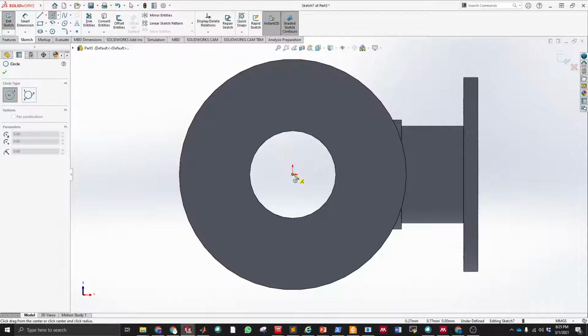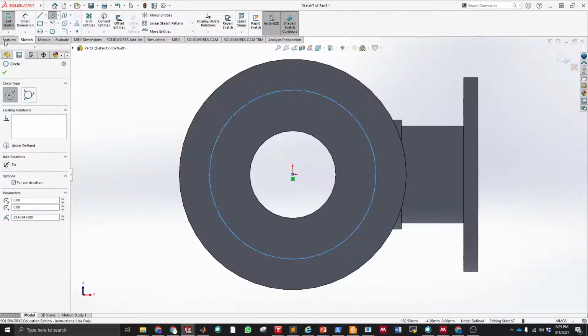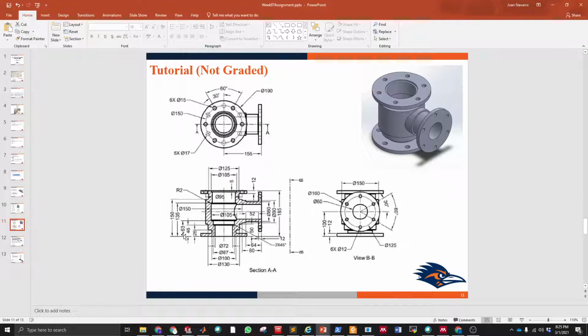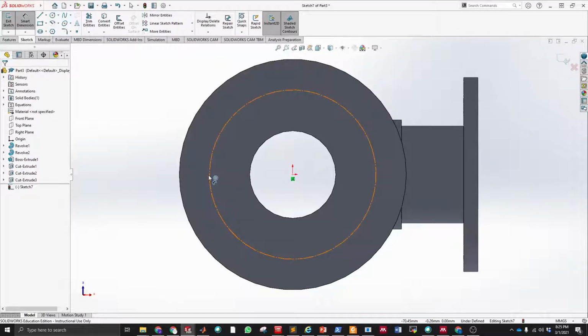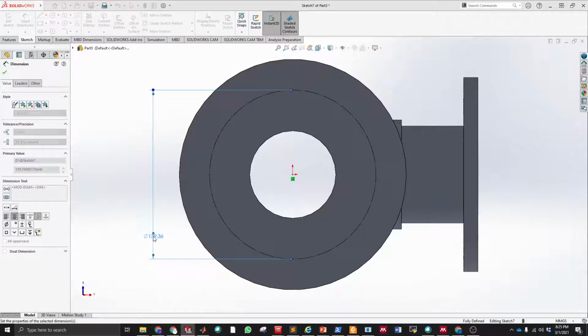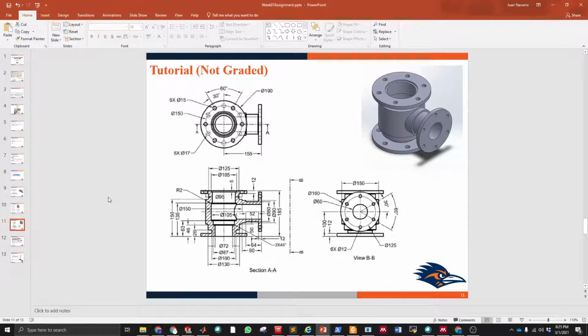A circle for construction. That is actually the same. And as you see here in the top view, we have the circles, like dark circles, that are in the top face. But then there is a mismatch from the circles in the bottom face. The circles in the bottom are aligned with the vertical line, not the horizontal. That's why we have some of those circles with hidden lines.